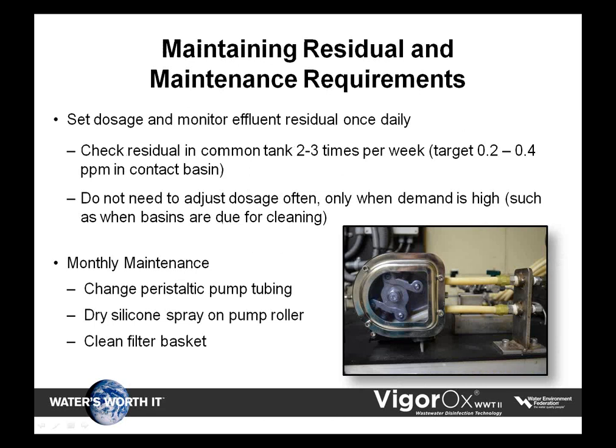As far as maintaining a residual, all we do is set our dosage and we're done. We don't need to make many adjustments at all unless our demand changes, which typically would only be if our basins are nearing time to be cleaned. When we check our effluent residual, if we do get a low reading, we check our common tank residual to make sure that there's no issues with the system. And like I mentioned, when we get the new version of the analyzer, we're hoping to have it at this location, so it'll help us with the monitoring.